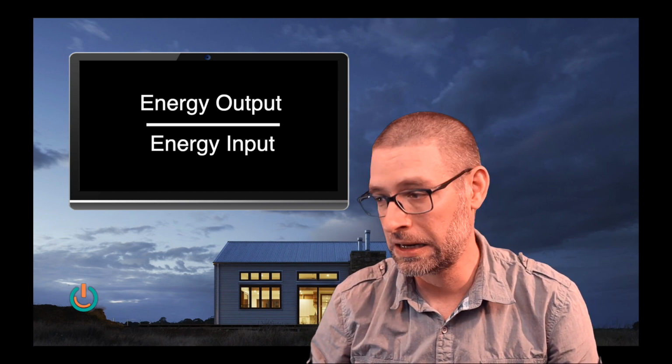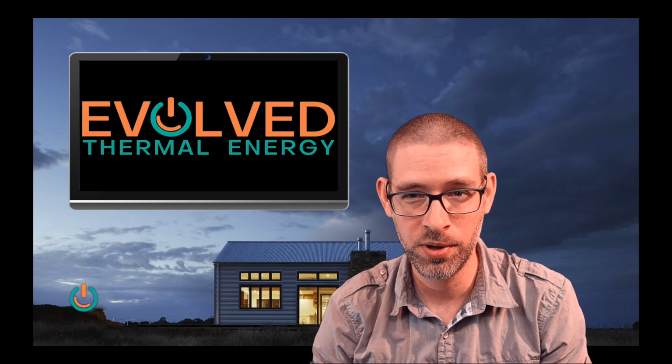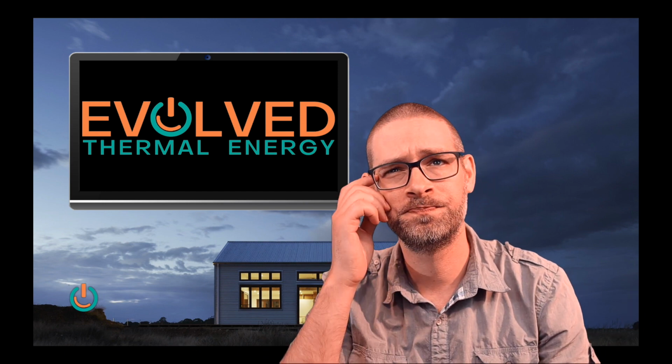We would just hook up an electric heater to heat our house. An electric heater is 100% efficient. We plug it in, we get 1 unit of energy from the grid. That equates to 1 unit of thermal energy of heat. So it's 1 for 1, 100%. So if we're going to go through all this trouble of a heat pump and a ground loop, we're going to want a heck of a lot more than 100% efficiency from our system, which we can get.